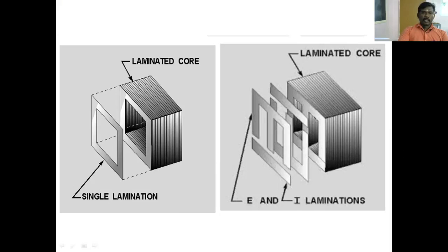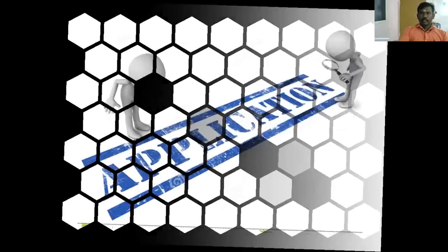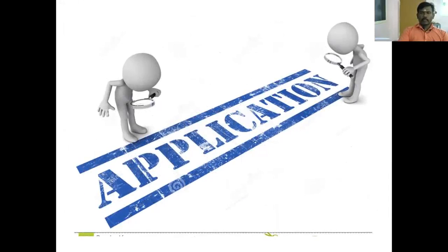Using thick metal produces an enormous amount of eddy current. To reduce that eddy current, we alternatively use thin laminated sheet. And another alternative way is to drill a small hole in the thick metal. Make a small hole in a thick metal, it also reduces the eddy current.